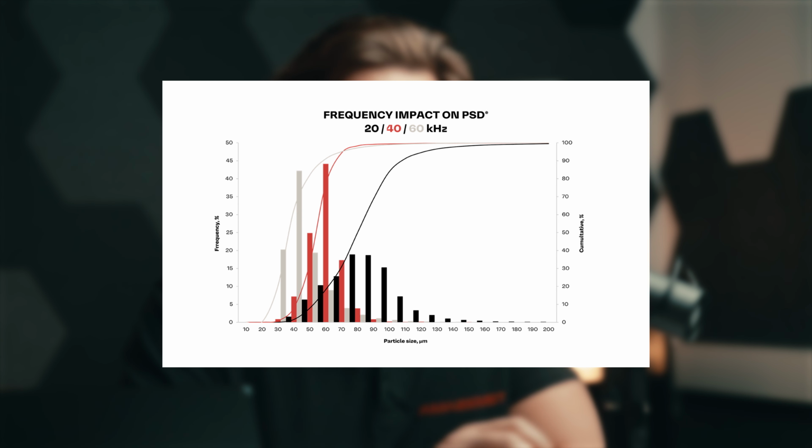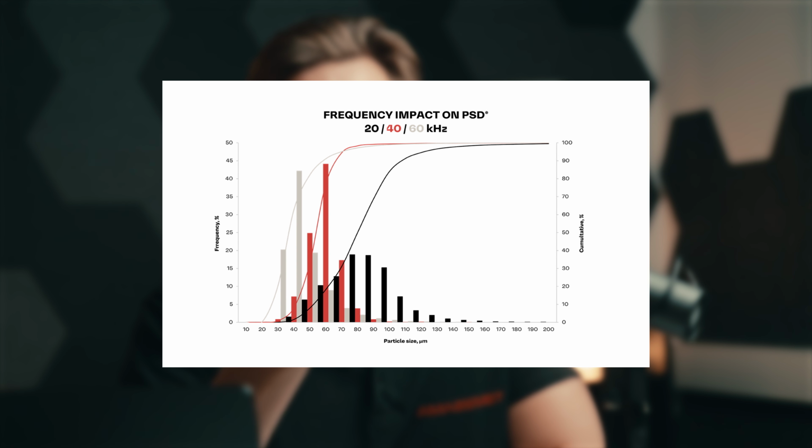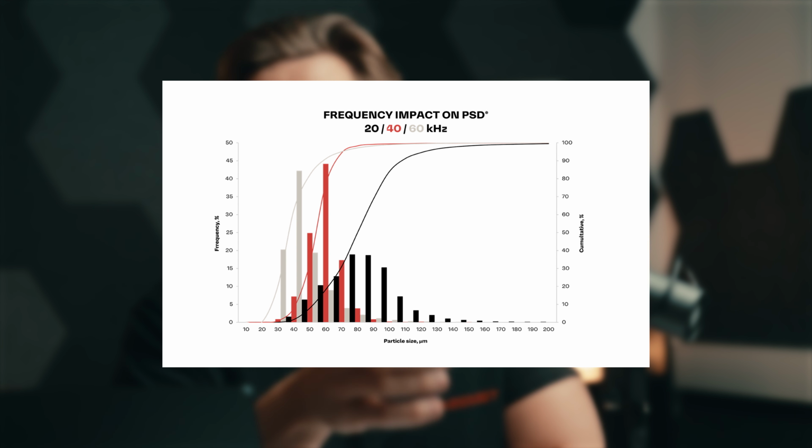The Sonotrode itself is bulky, but the higher we progress with ultrasonic frequency to reduce particle size distribution, the finer and finer those Sonotrodes get. For example, a 60 kHz Sonotrode is as little as 1/3 of the 20 kHz Sonotrode. And keeping it cool at the node is a much harder task than in the case of 20 kHz. The other thing that we have to understand about the Sonotrodes is the materials they are composed of.